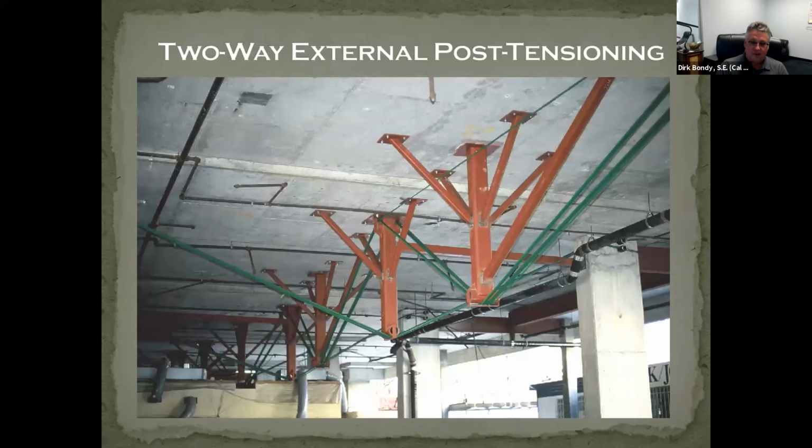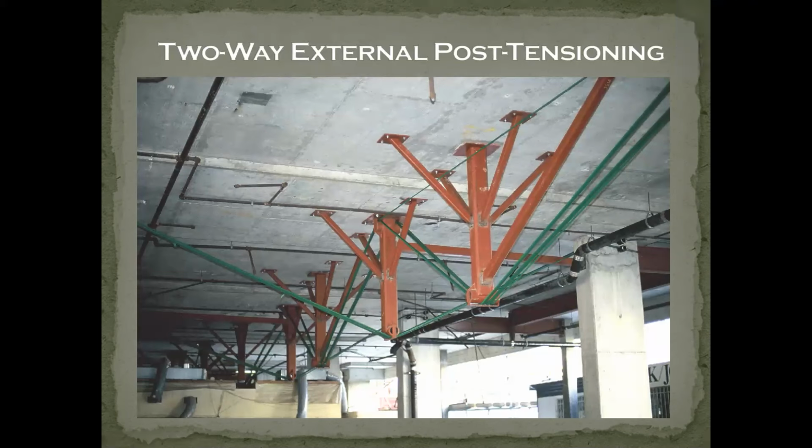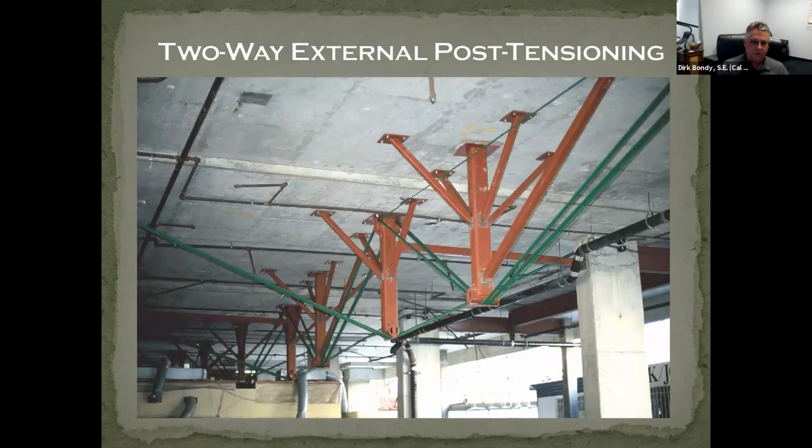This is a particularly aggressive external post-tensioning job that my father did. This was a case where it was about a 12-story building in Los Angeles. There was no headroom in any of the floors up above, but there was plenty of headroom in the lobby area at the first level. So all of the jacking happened in that lobby level, and above these were 12-story columns running all the way through the building. And the theory is dropping off equally, lifting each floor 1/12 of the load. It seemed to work, and it's still standing to this day.